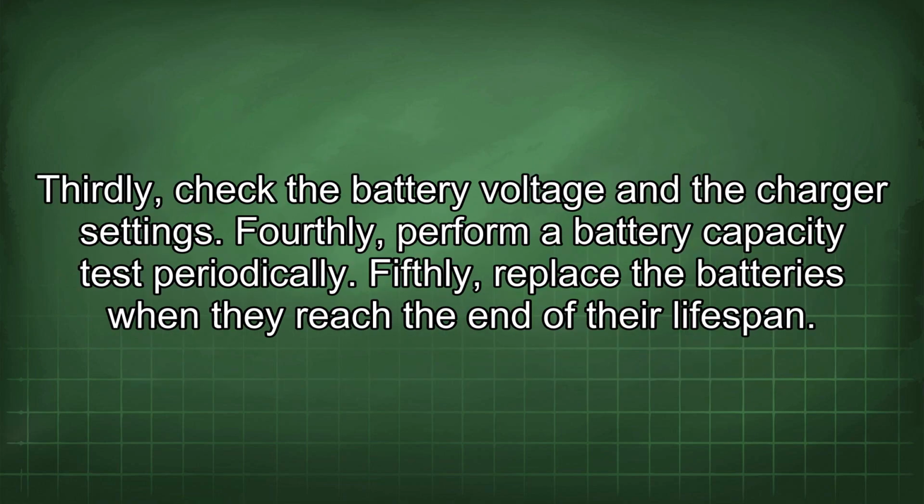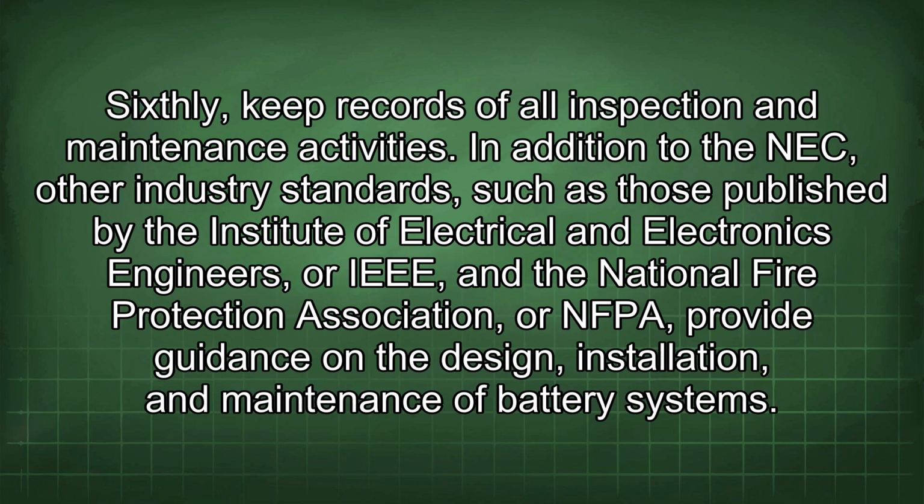Thirdly, check the battery voltage and the charger settings. Fourthly, perform a battery capacity test periodically. Fifthly, replace the batteries when they reach the end of their lifespan. Sixthly, keep records of all inspection and maintenance activities.